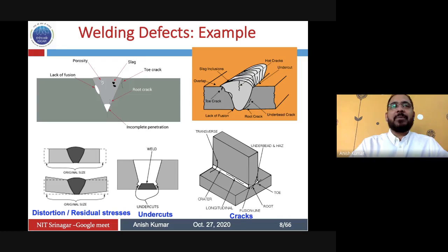any kind of fatigue damage, fatigue crack initiation, which basically depends on whether on the surface you have tensile stress, which can help in generating more fatigue cracks on the surface, or you can have stress corrosion cracking, which will happen more if you have a tensile stress in the sample. So sometimes it is also important to measure the residual stresses, which I'll show